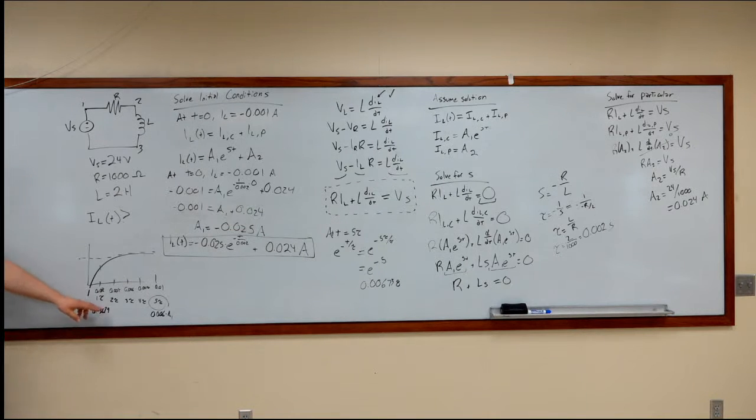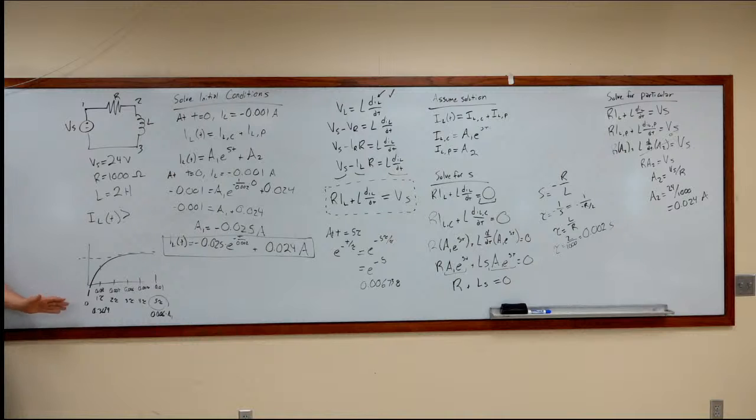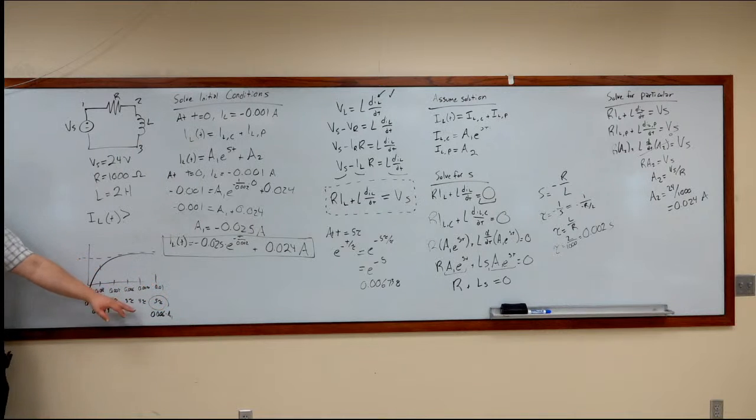But looking at it in terms of tau, from 0 tau to 5 tau is going to show us a progression of where we start to where we reach steady state. I don't care about the solution past 5 tau, because this is an analog system, there are going to be changes in Vs. Vs may vary by 0.02 volts, sometimes even more.